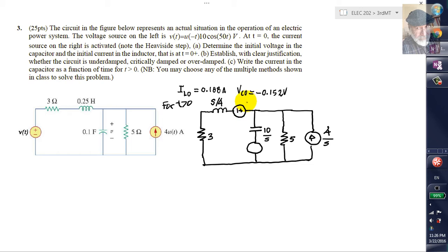they point in the direction of the initial condition. The current in the inductor was flowing from left to right, so that's why that source has that polarity, left to right. And the value is L times IL naught. And you're thinking, why are you writing 0.188 as 188? Because I will divide that by 1,000, and I'm dividing that by 1,000 because the HP50G and most other symbolic solvers prefer using integers.